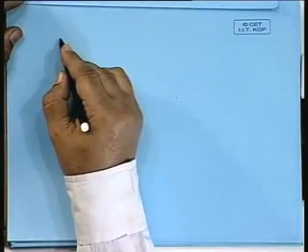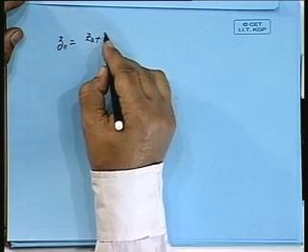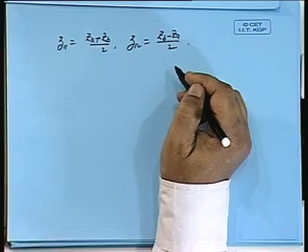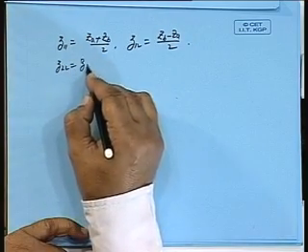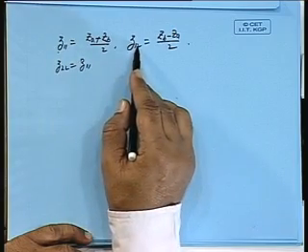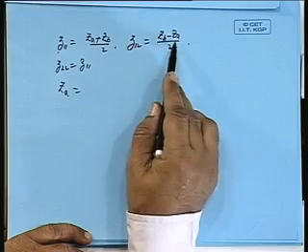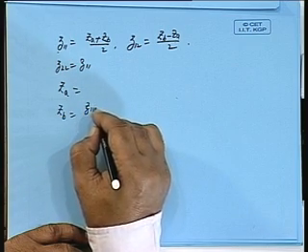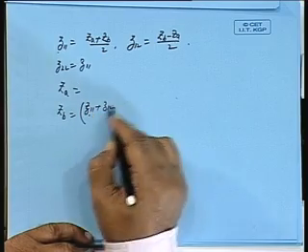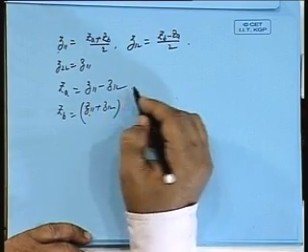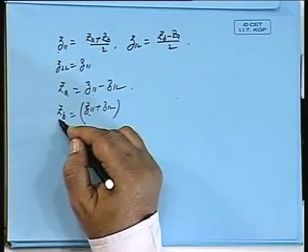So, we have got two interesting results. Z11 is ZA plus ZB by 2 and Z12 is ZB minus ZA by 2. Z22 in this case is same as Z11. So, if you are given this Z11 and Z12 as the specification, ZB is this plus this, and ZA is this minus this, Z11 minus Z12. Just subtract Z12 from Z11, you get ZA, add, you get ZB, and hence synthesize.